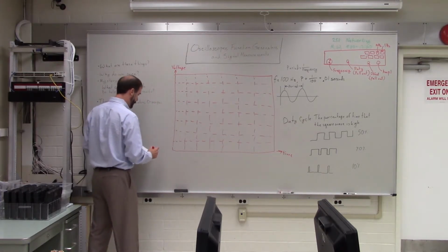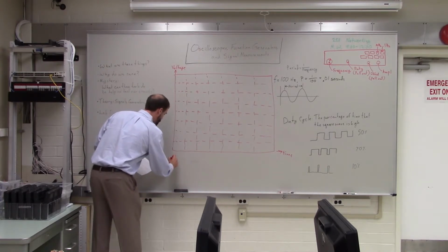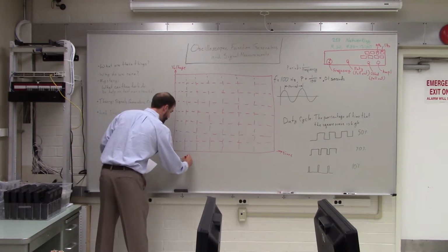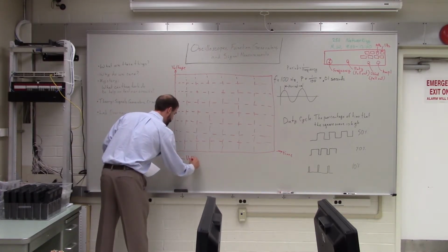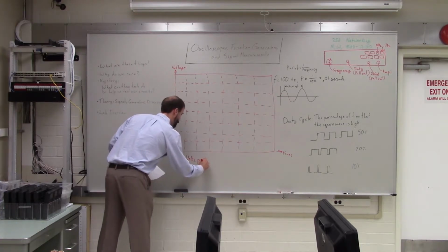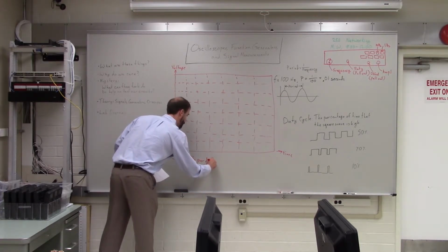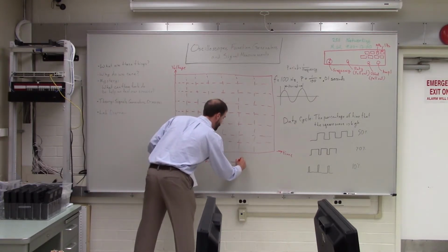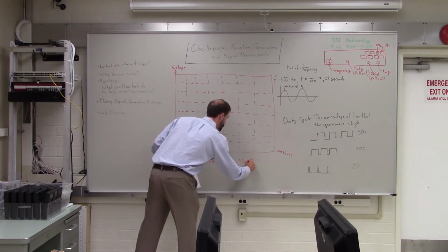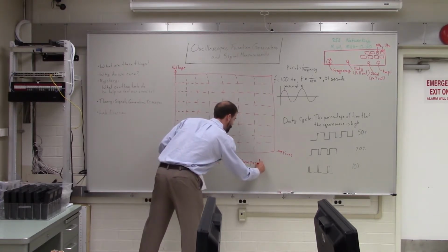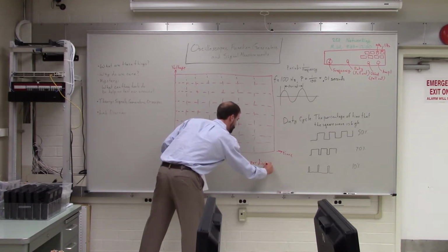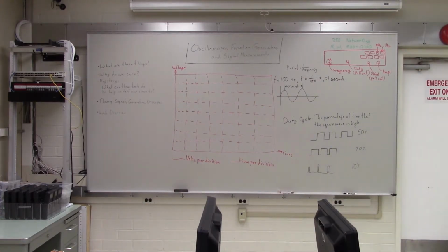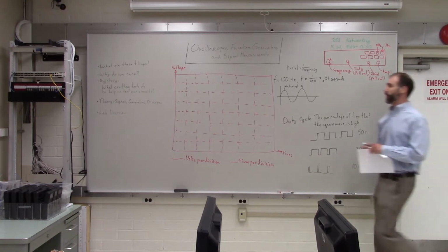So down at the bottom of the screen, there is always a little field that tells you the volts per division, and then another one that specifies the amount of time per division. Okay? So we can look at those and look at our signal and get an idea about what's going on.